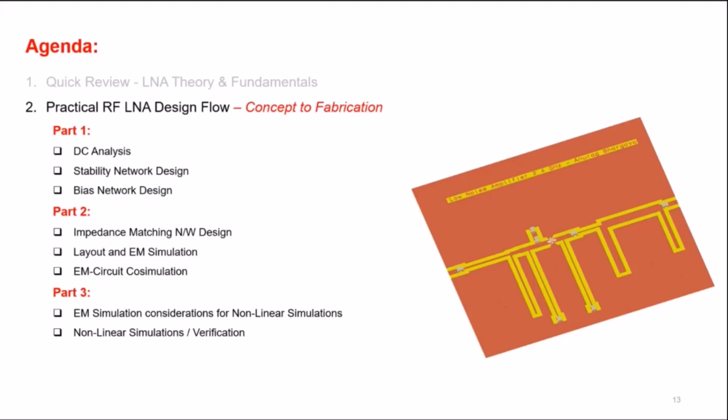Can we do impedance matching using inductor and capacitor for frequency up to 4 gigahertz? That might be challenging because capacitors, no problem. You will find capacitors easily going to that frequency. You will have problems with inductors. So I would say at 4 gigahertz, you can directly do a full distributed matching based design, or you can even do a hybrid design where inductors are implemented using transmission line and capacitors are picked up from SMT vendors like Coilcraft, Murata, or such vendors.